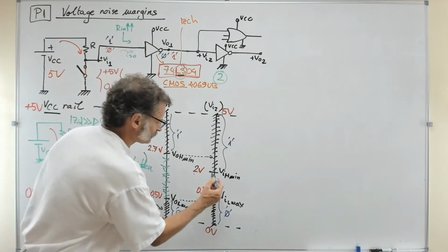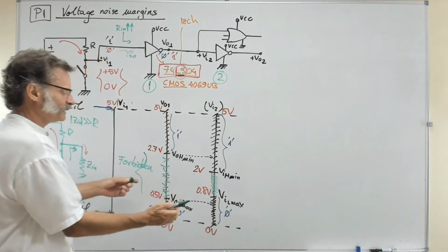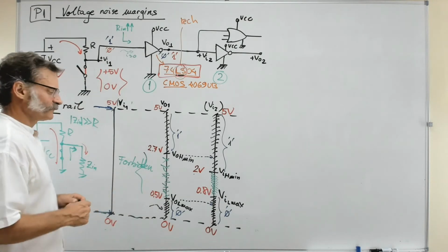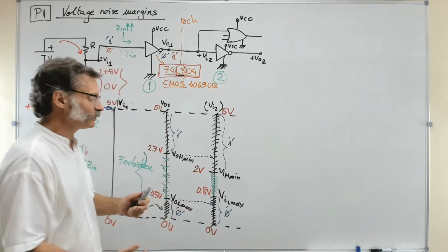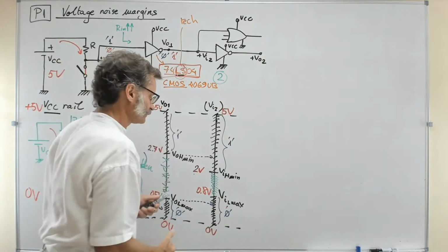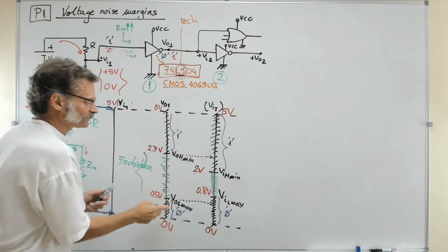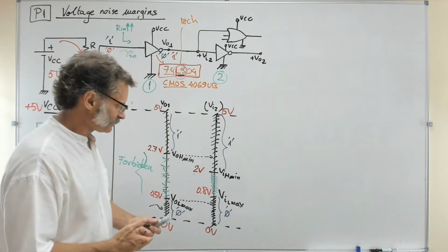So here is the same thing. This zone has no meaning. It is for avoiding. You'd better not use it, because you will never know what is going to happen at the output of the circuit if you are driving the input of a gate like this with a voltage, for example, of 1.5. Who knows what is going to happen?